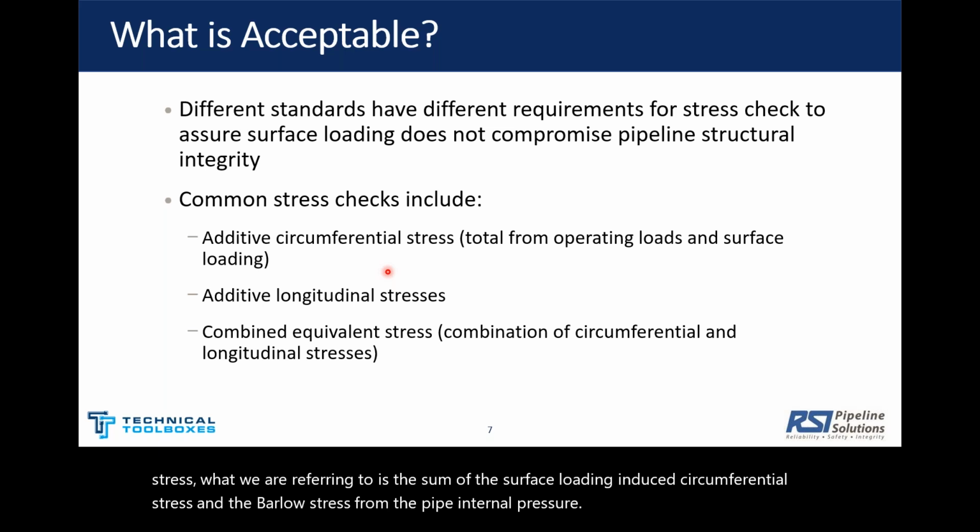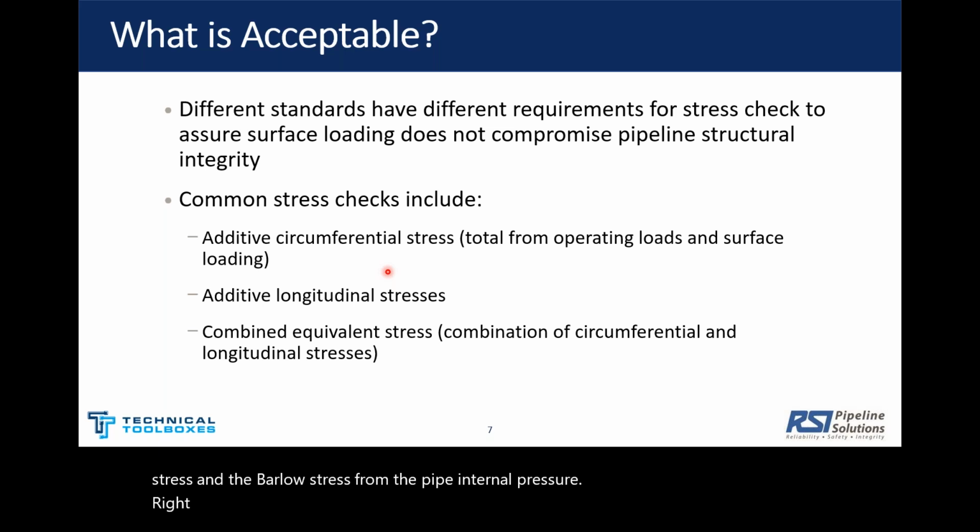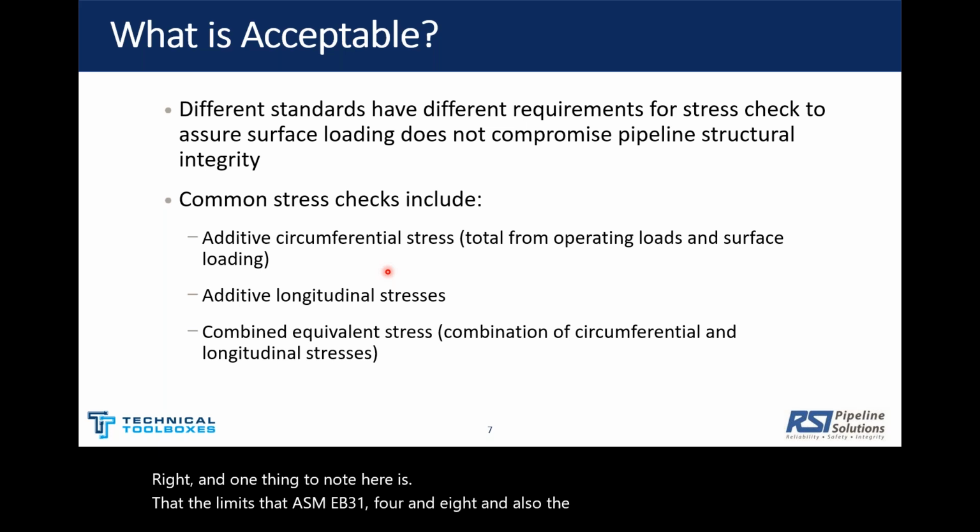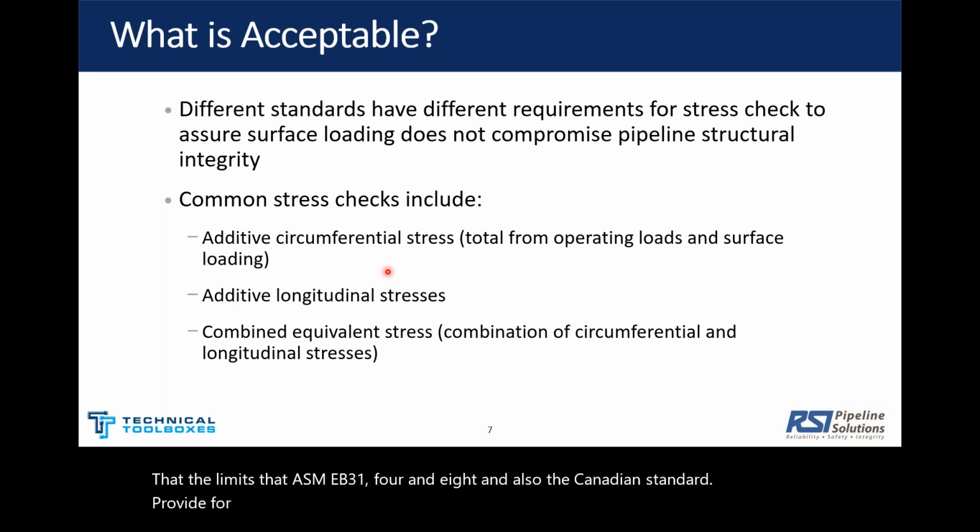And one thing to note here is that the limits that ASME B31.4 and B31.8, and also the Canadian standard provide for the surface loading analysis is actually more than 72%, right? So your circumferential stress is not necessarily limited to 72%.